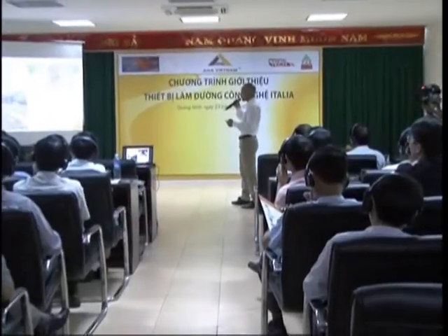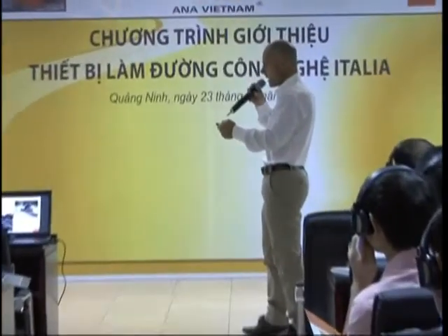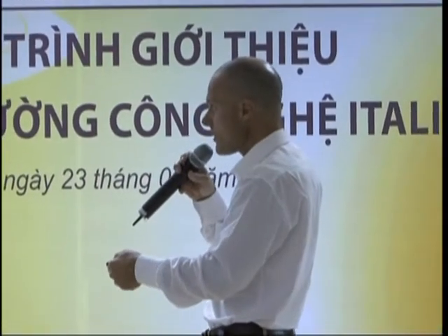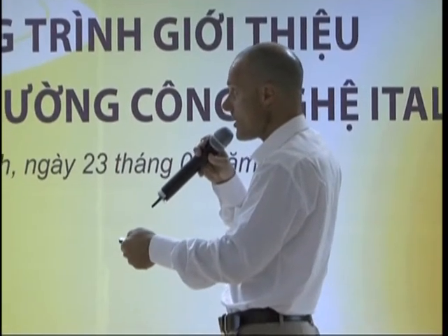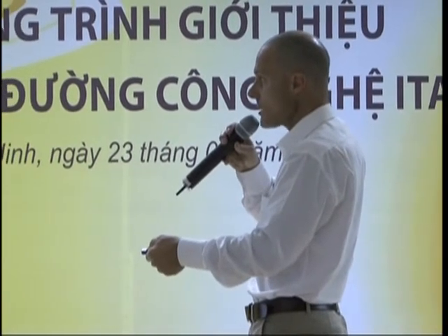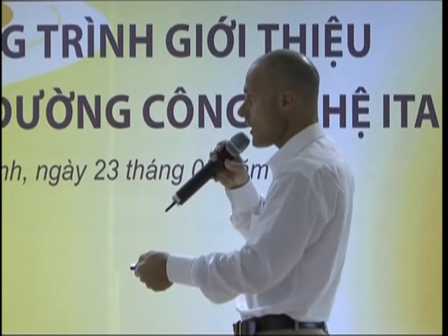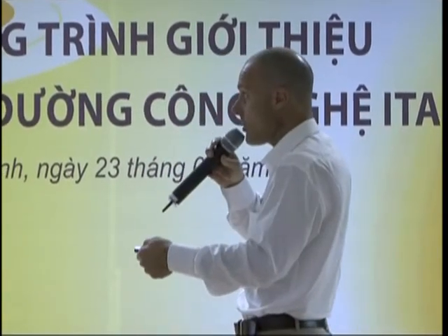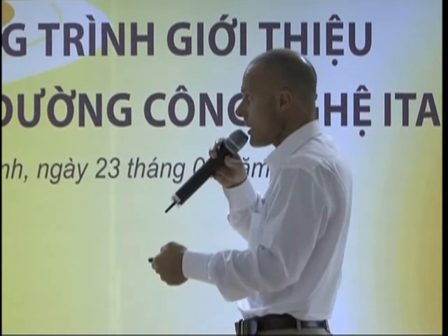This is a job we did with this company, Renolit, in Indonesia. This is a mine road in Indonesia, for example, gold and copper mine. And what they did, as you can see here, they ripped. Always rip first, it's better. They put, in this case, cement and silica, cement and sand. They put it by hand in this case because they didn't have a machine for cement, no problem. People put cement by hand.